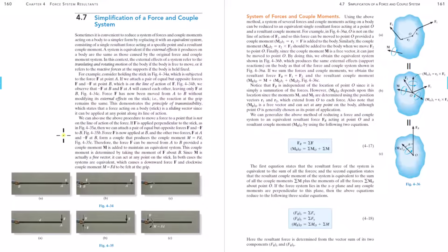If you can't put the tails of the force or moment vectors together, then you can't sum them. That's pretty much what we learned in the vectors in space video. We did do the head to tail method, but first you had the vectors with their tails together, and you could leave their tails together and use the parallelogram method, or you could use the head to tail method, get the resultant vector with its tail also at the tail of the two vectors, and then bring that original vector back. It was kind of implied that if you're summing vectors, their tails are together.